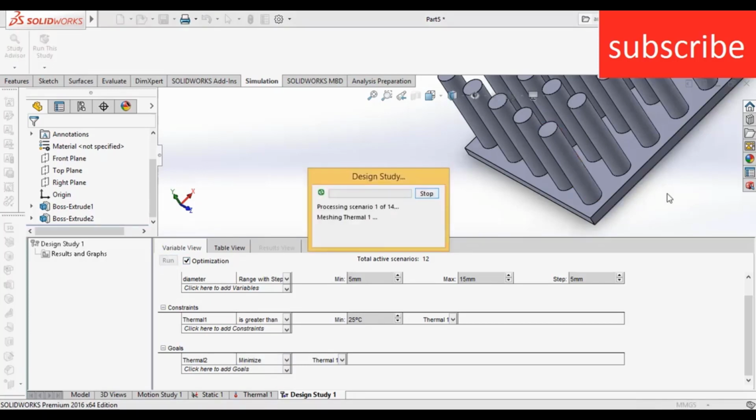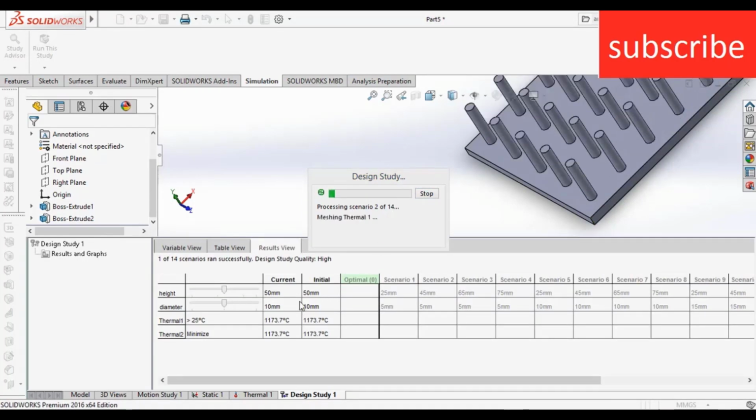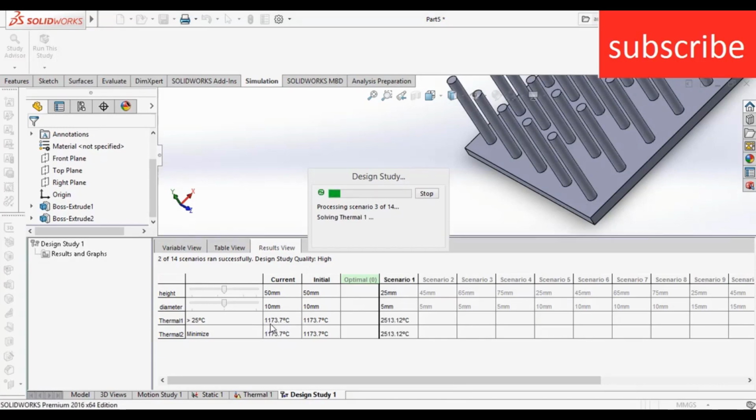Now let's see what's happening in the background. As you can see, it's currently processing the scenarios. Here you are watching the table. For example, the initial height is 50 mm, the diameter is 10 mm, and the initial temperature is 1173.7 degrees Celsius. Now it runs the first scenario.